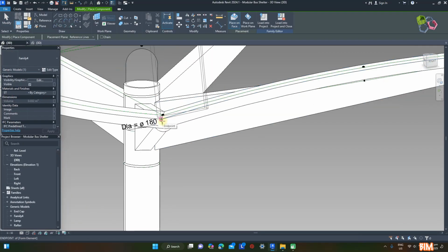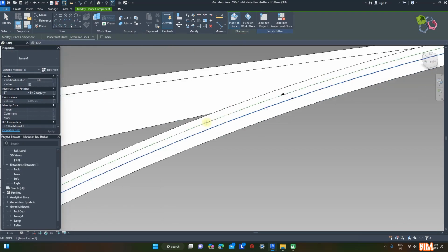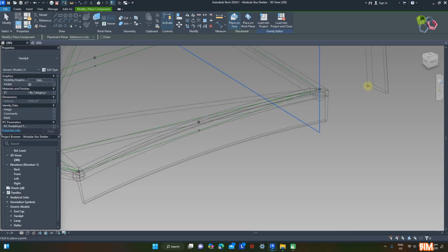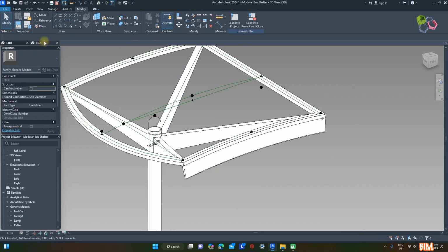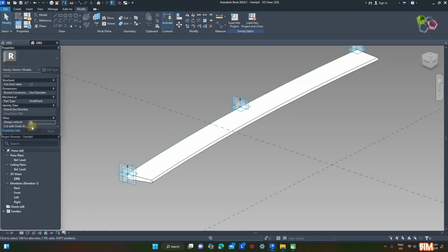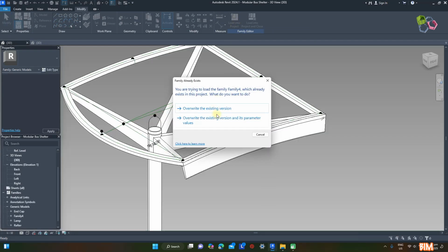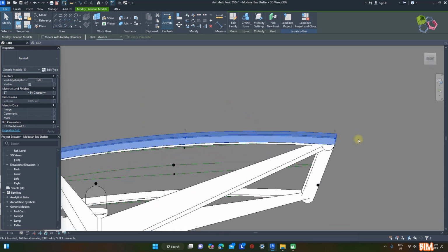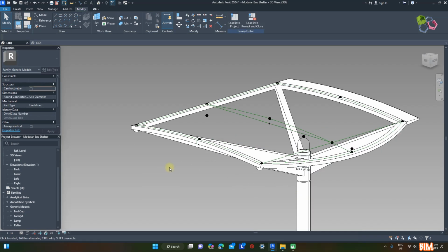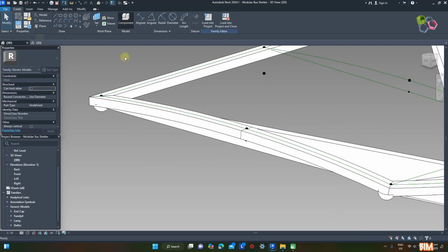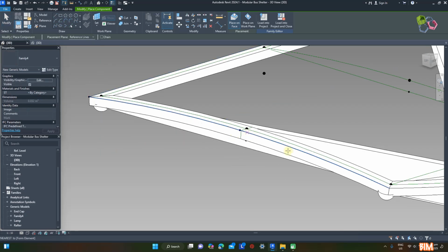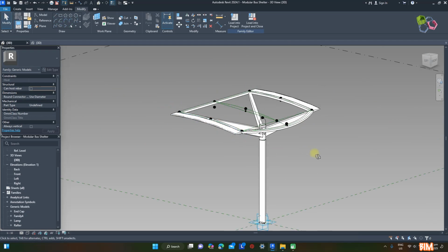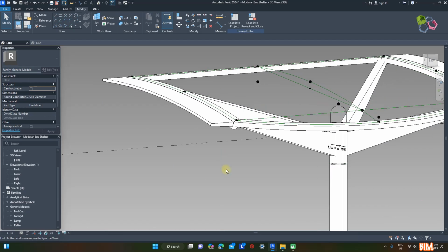Load family to main family as nested, and install on the roof frame side. Do need family modification: back to the family and check the option for always vertical, load and overwrite the existing one as required. Install for another side. Rename for end shade.